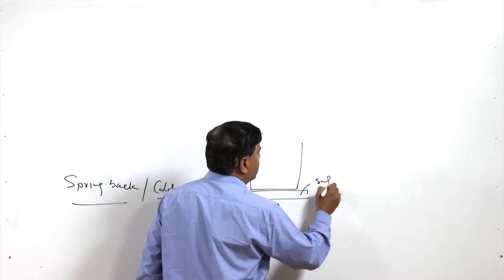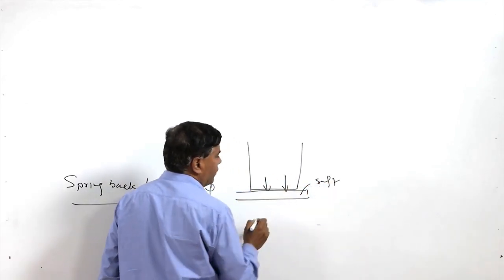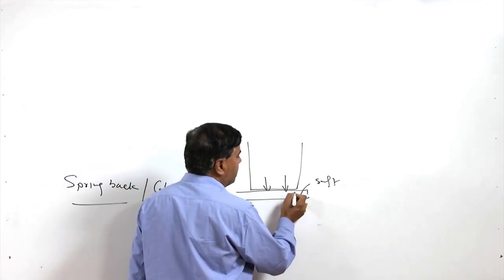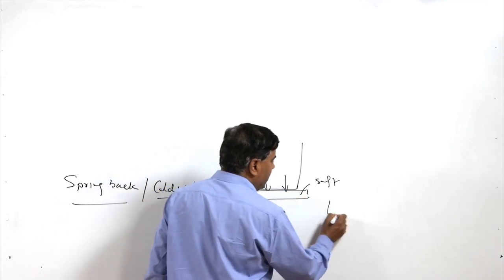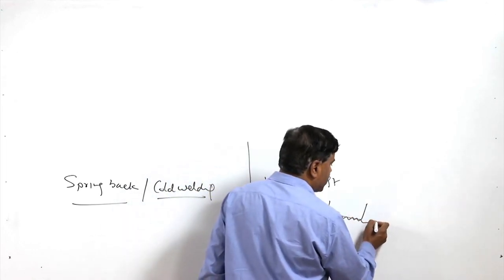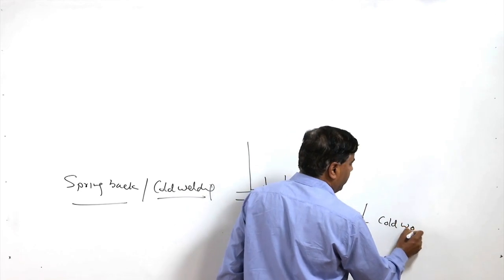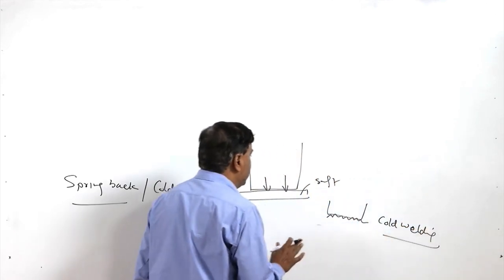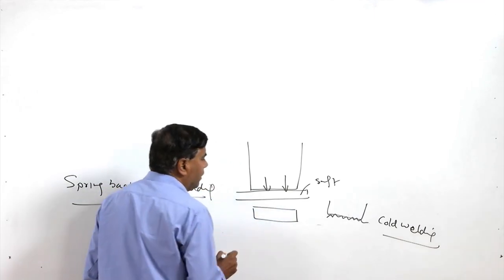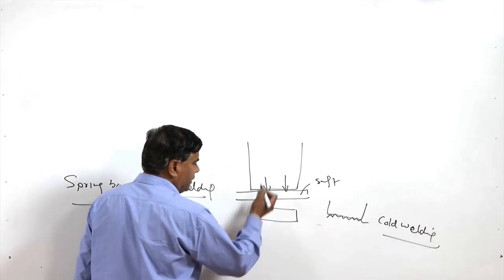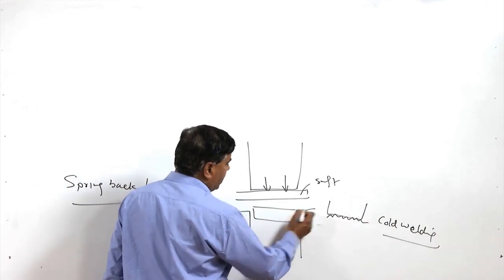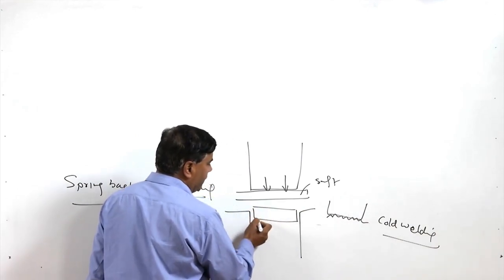If the sheet metal is soft, the punch puts a lot of compressive force onto it, and because of this the sheet metal sometimes gets embedded with the surface of the punch, even under low temperature conditions. This is called cold welding. Because of it, even after shearing, the slug may remain attached to the punch, or it may get attached to the die.